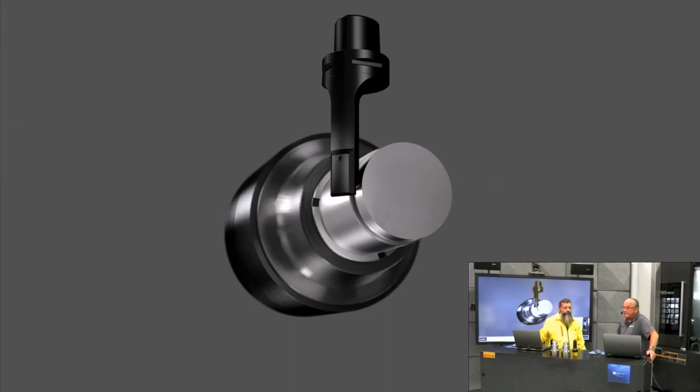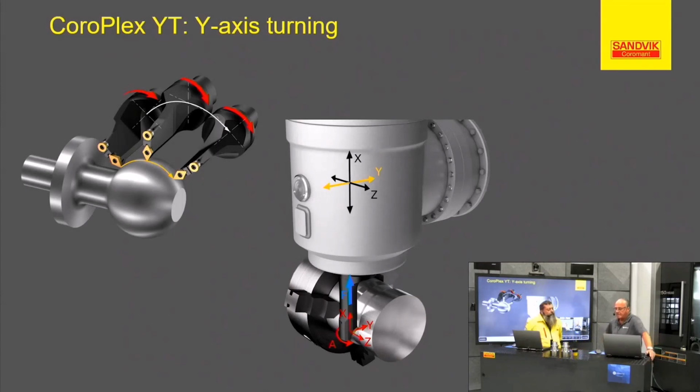Well, the way those tools are designed is just fantastic. And like you said earlier, the cutting pressure gets pushed up into the spindle, and that's where the tool is the most rigid ever. So there is no deflection on the tool, or very little. Most of the cutting pressure gets into the spindle, and that's where the rigidity comes from.